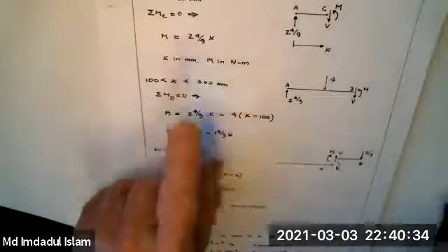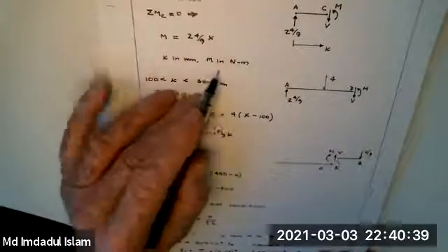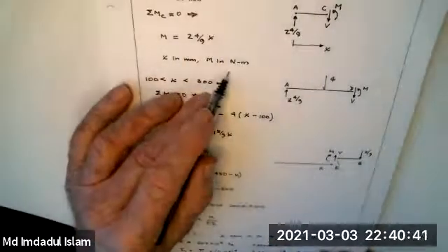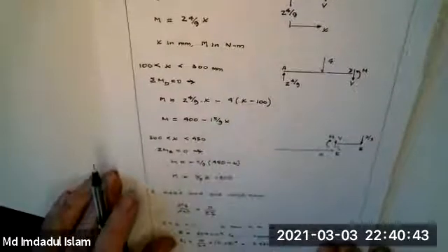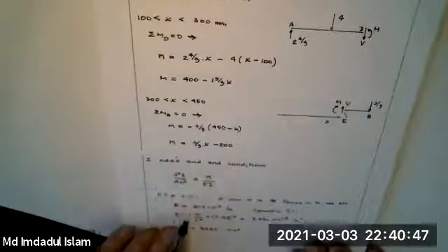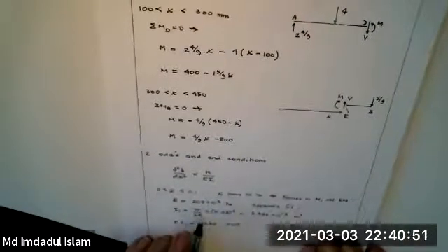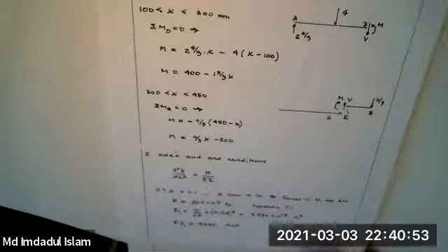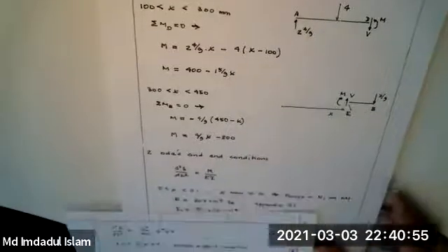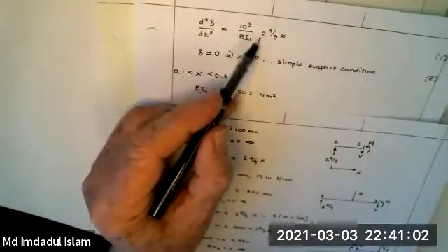Now this force here was in kilonewtons. So if X is in millimeters, at this point, you're getting M in newton meters. When you start to set up your ODEs, you better switch all to newton meters. And so you put X in meters, then you change your forces to newtons. Otherwise, once you start to integrate, you'll get inconsistent units. What's going to happen here is this went to 10 to the 3 because it went back to newtons, and now X is in meters.